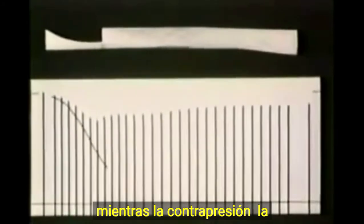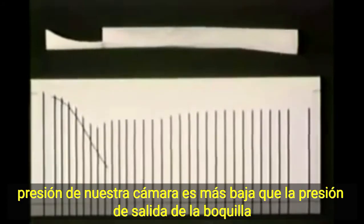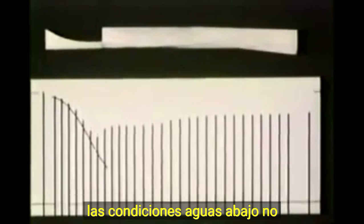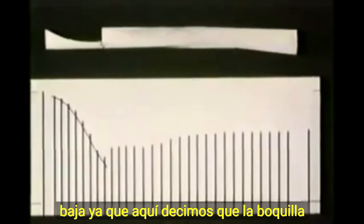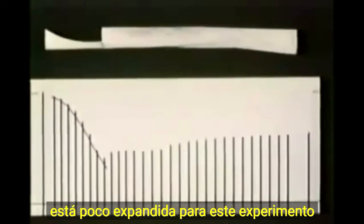As long as the back pressure or chamber pressure is lower than the nozzle exit pressure, downstream conditions do not affect the flow in the closed part of the channel. When the back pressure is low, as it is here, we say that the nozzle is underexpanded.